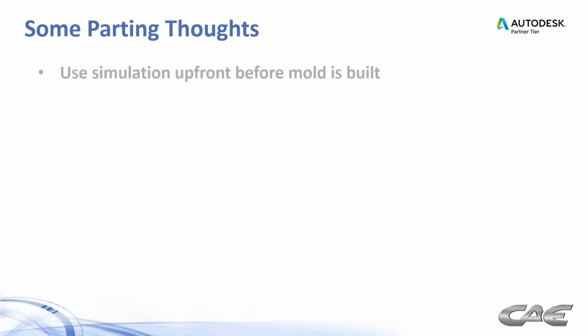So, some parting thoughts here. Use simulation up front, before the mold is built. I'll say it time and again. It doesn't matter if it's appearance issues or warpage issues or processing issues or any issue you can think of with plastic injection molding. Do the simulation up front. Don't wait till the last minute, because you're asking for trouble.